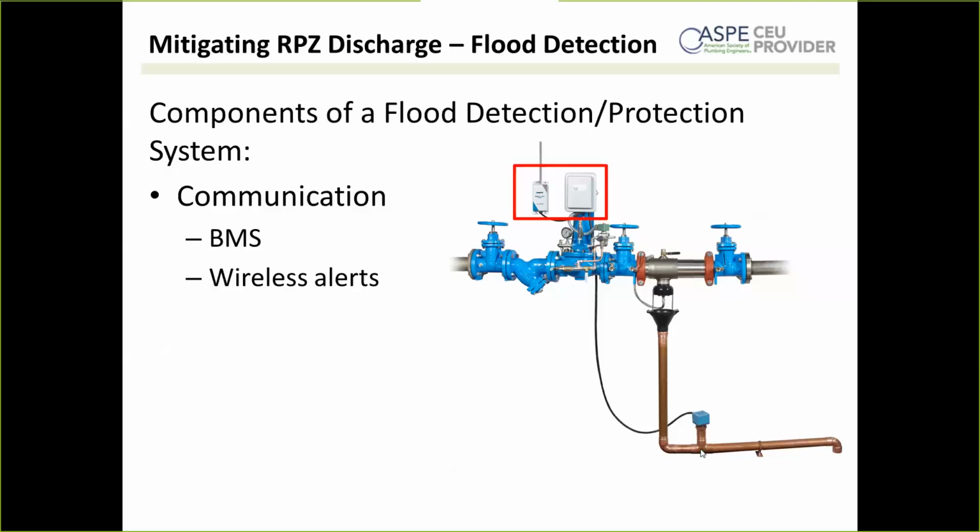Yeah, I would say it's a good idea. Maybe annually pour some water down that discharge line and observe it. If you have the shutdown valve, make sure you're doing it at a time where if you shut down the water for a few minutes, it's not going to be a big deal. So observe it, make sure you're getting the alerts, make sure everybody knows they're going to get the alerts and to ignore it. Let it trip, get the system back up and running, and give yourself a nice little run through to make sure everything's hunky-dory.